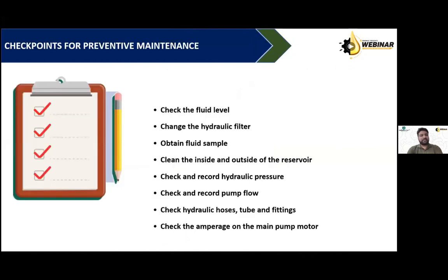There are certain checkpoints which we always leave with our audience before signing off. These are the checkpoints which you can follow. I'm sure many of you have them on your daily maintenance list, but just to remind those who might require it. You need to check the fluid level. You need to check the condition of the hydraulic filter. By checking the condition of the hydraulic filter, we mean the DP values, or differential pressure values.